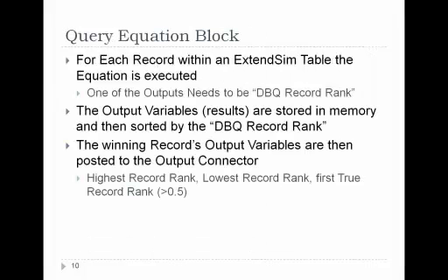One of the blocks that provides a very powerful way of controlling the model, and it's my understanding that it is an absolutely unique feature to Extend, I haven't seen it in the other modeling tools that are out there right now, is the query equation block. What the query equation block does is something very unique. For each record within an ExtendSim table, the equation is executed.